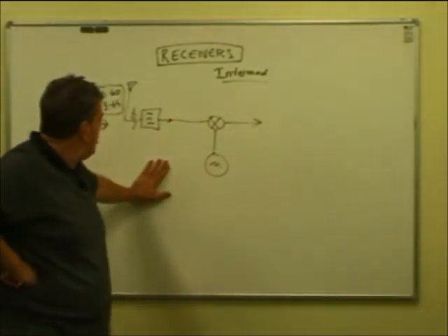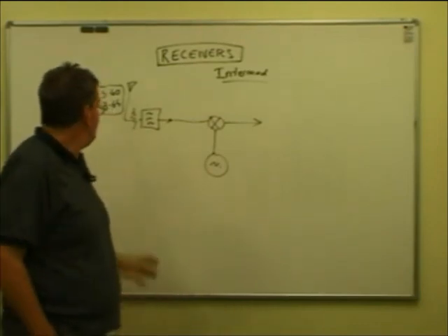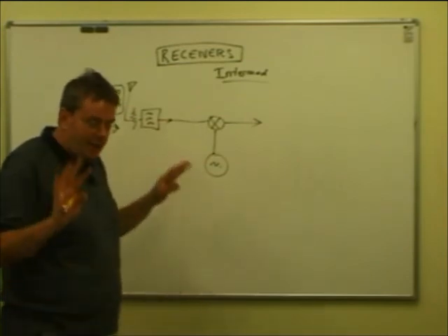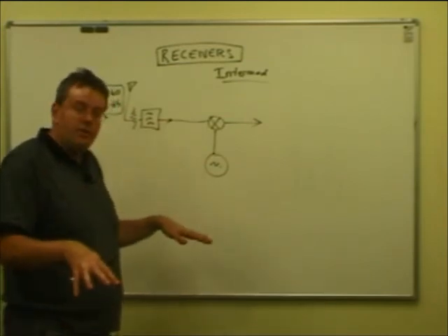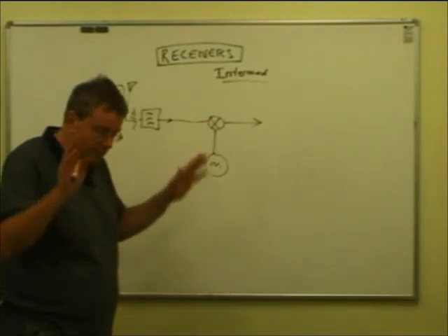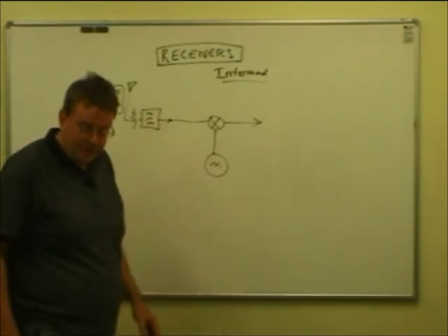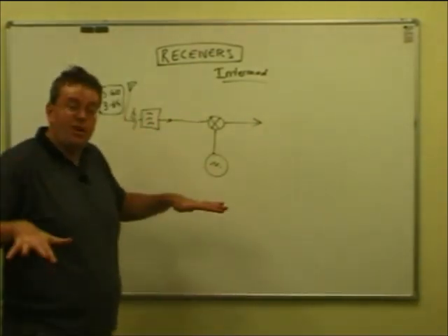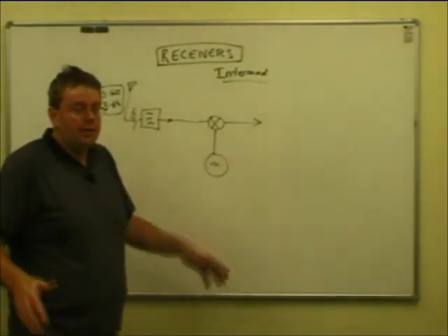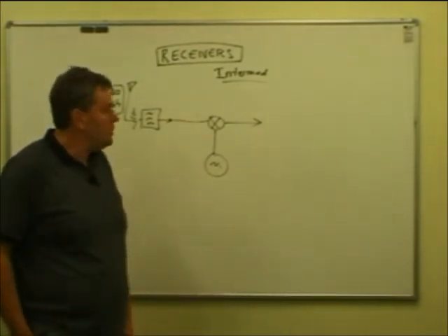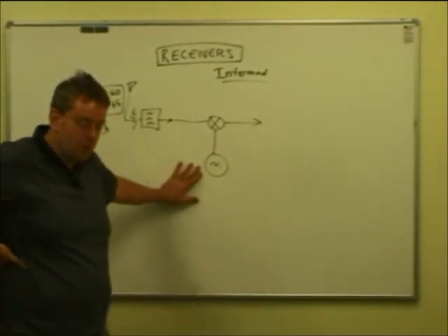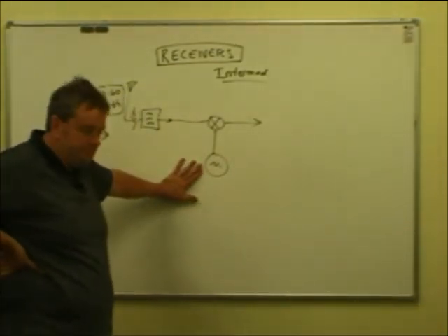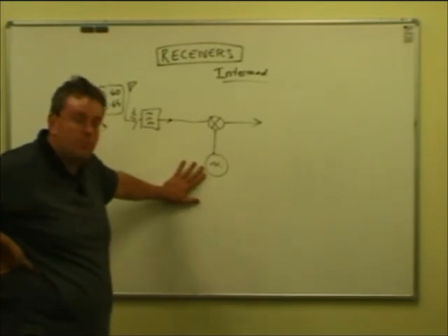you can help stop that intermod from happening by switching the attenuator into your receiver, and it will drop down the strength of everything, and it will tend to make those intermod products drop down much further, or even vanish altogether. When you're getting intermod taking place, if you can just reduce the strength of the whole lot a bit, you'll drop the intermod by a bit times 3. So that's why it's an advantage sometimes, although some of the weak signals might vanish, at least you can make life a lot easier for yourself. I hope I haven't confused you too much.